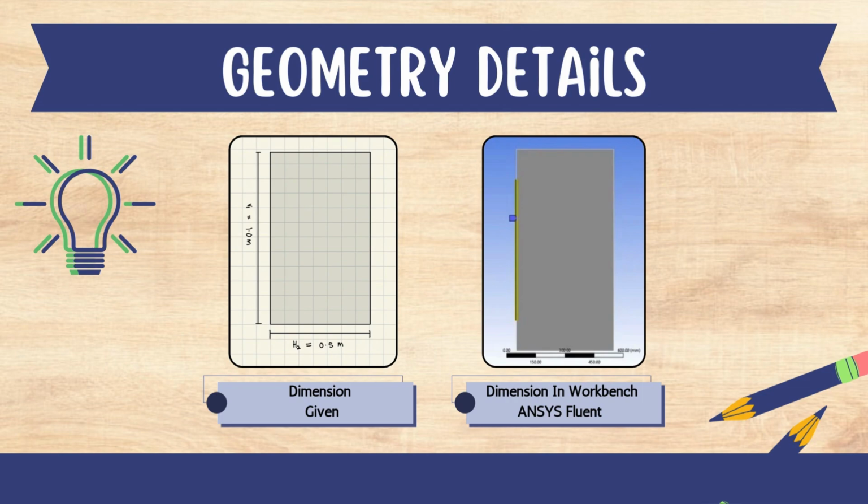Next, let's discuss the geometry details used in this study. Dimension given. On the left, we see the initial geometry with the given dimensions. The height of the domain is 10 meters, while the object's height is 0.5 meters. Dimension in ANSYS Fluent. On the right, we see how this geometry was implemented in ANSYS Fluent. The dimensions were input accurately to ensure the simulation aligned with the theoretical model. This step ensures that the computational setup matches the intended design for accurate flow analysis.